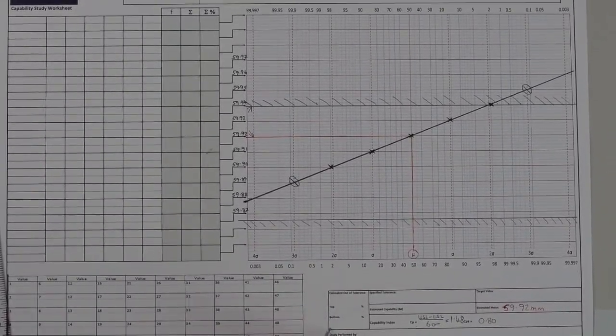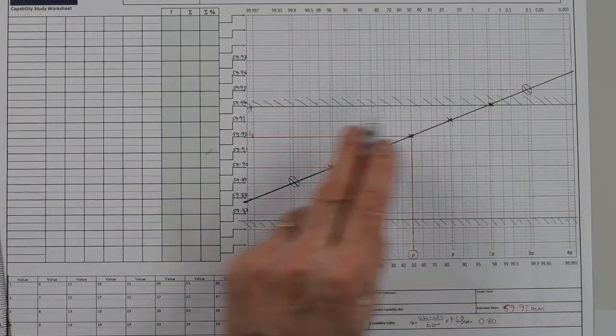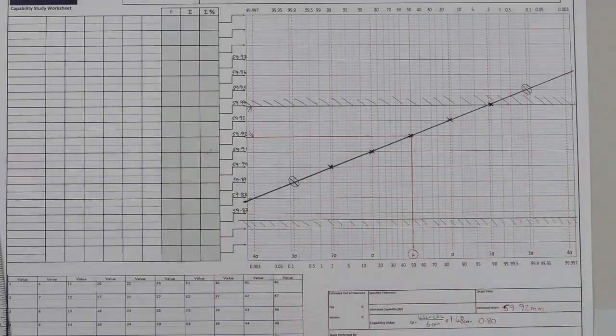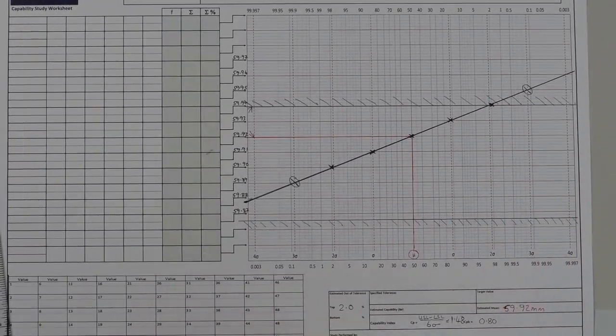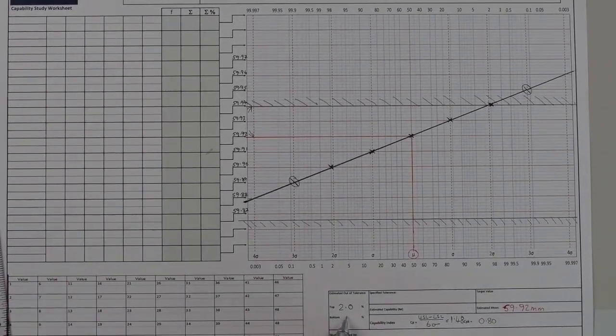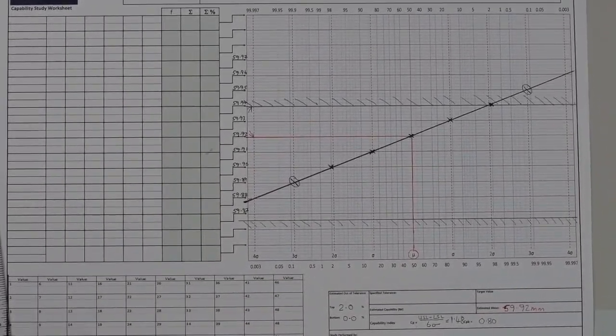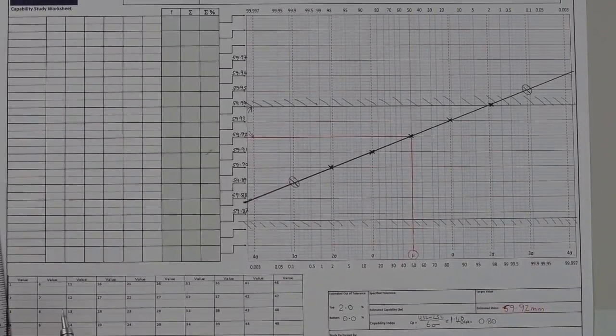We can complete the out of tolerance measurement. At this point here, which is at the 98% point, we get 2% failures at the top level, and at the bottom we get no failures that we can see in the graph, so we say 0.0%. So only having the 5 points displayed on the graph, we can still derive the same information as we derived from the previous calculations.